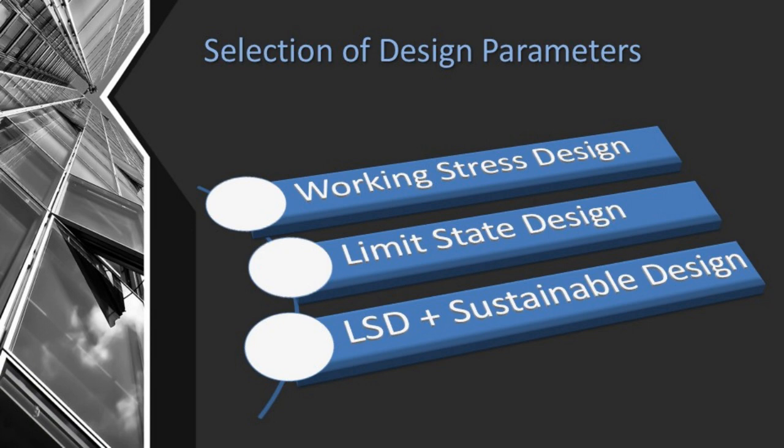When we came to know about the tension properties of the reinforcement, we redefined the design methodology and came up with the limit state of design. There we actually design an under reinforced structure, so that whenever the structure fails, we first get the warning because the tension zone fails first. So you get the warning before the failure, and then you make your structure safe. So in limit state design, you have stability as well as durability.